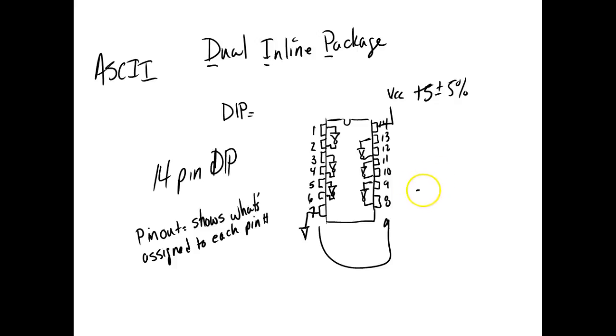So if I was going to wire this circuit right here, how would I wire it? Well, the first thing I'm going to do is look at my package and assign pins. I'm going to say pin 1. If this is the input, what would be the output? Okay, guys, if you got your book, look on page 51. This is the pin out right here. This is a 7404.